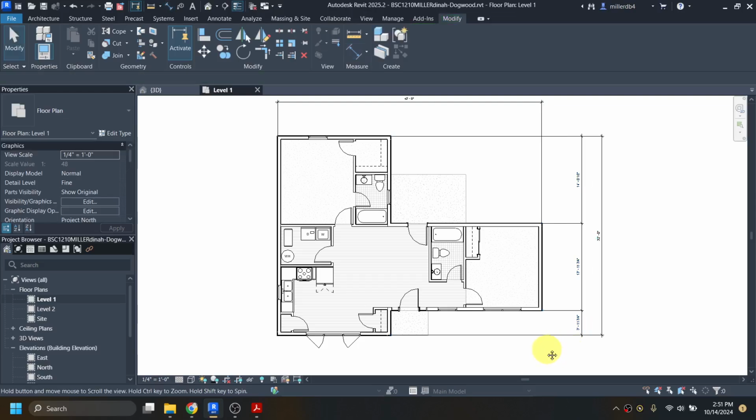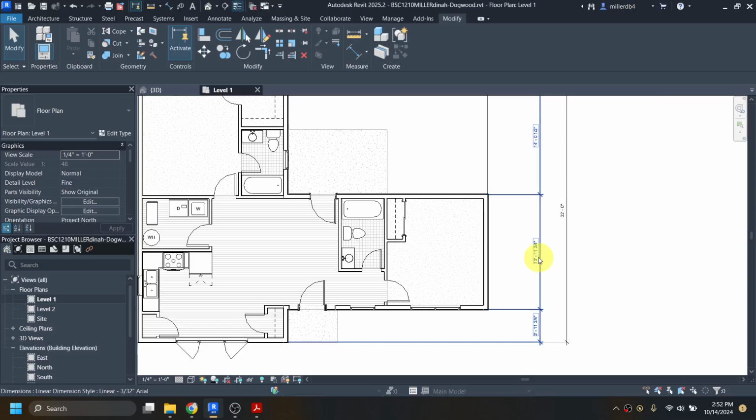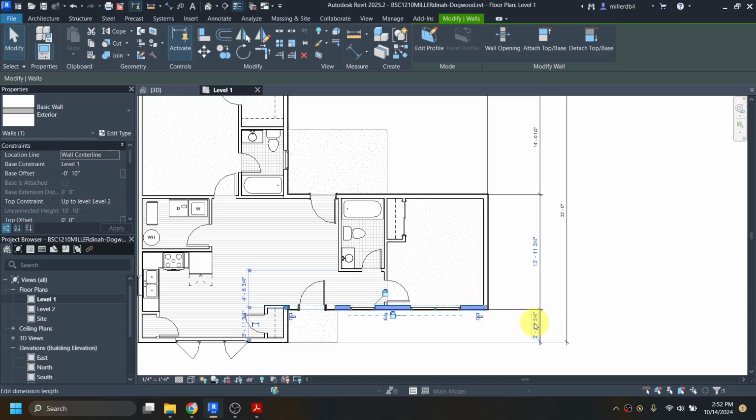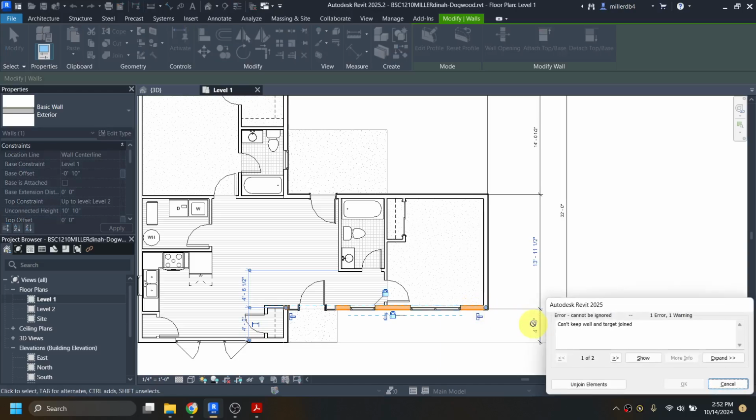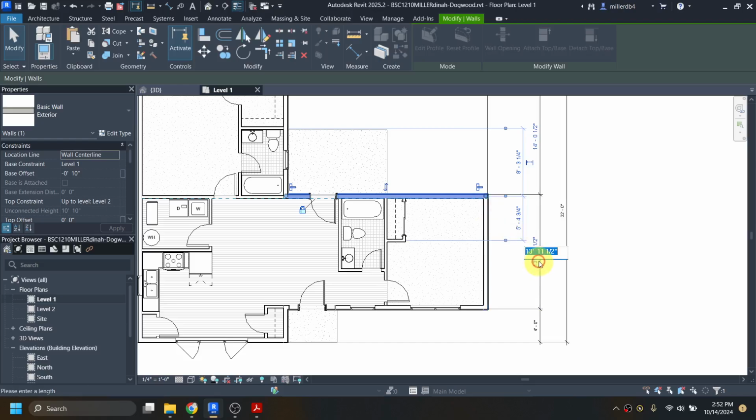Now, when you're moving these around, you want to kind of move in a sequence. So when I'm going to go change this to 4 feet, 14 feet, another 14 feet, I'm going to click on this wall, and I'm going to click on this, change the number. Let's unjoin and see what happens. It looks like nothing really changed, so that's good. But now if I want to go change this to 14 feet, what that's going to do is just shift that back down. So I need to kind of work my way up this sequence. So I'm going to click on this wall to change this number to 14 feet. And then that one changes by default.